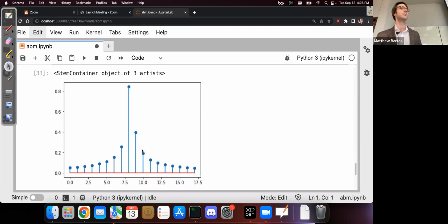Why is this format better than doing it the other way? Why do we want to do it with them on alternate sides? It's because when you look at an actual rainfall event, it'll generally have a peak in the middle. So it'll start off smaller, get big, and then return back to a smaller depth again.